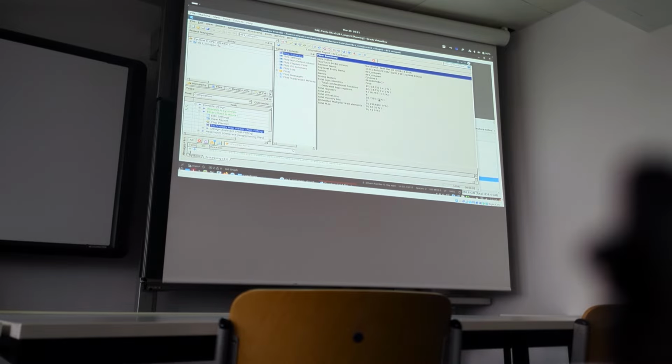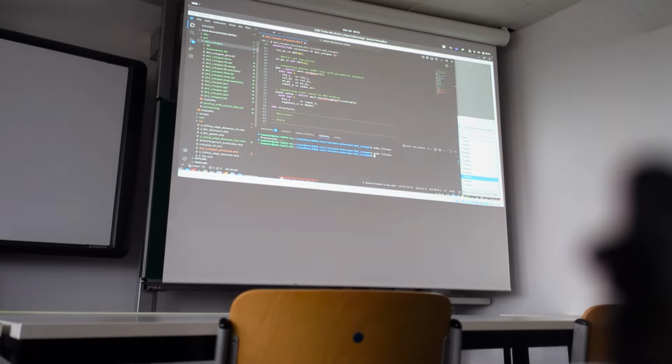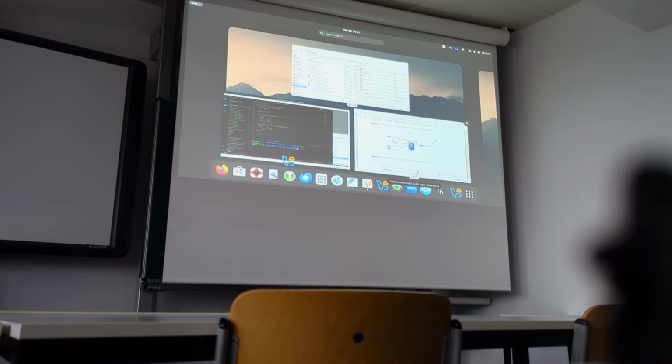And how many percent of the pins are used, how many percent of the total memory, multipliers, and PLLs are used, so all the components also available on the chip, which helps us designers to find out how complex our design will be. And if the other parts, which we have to design depending on our specification, will fit on the chip as well. So that was a short demonstration about the prototype environment.